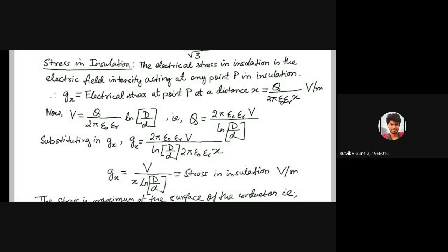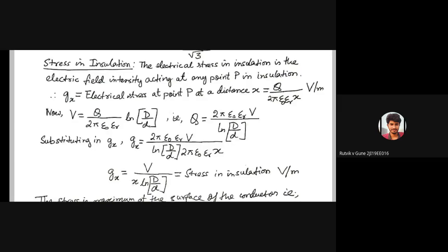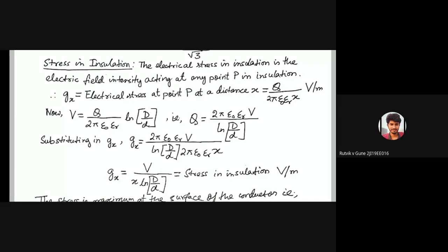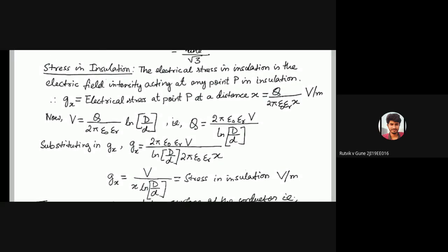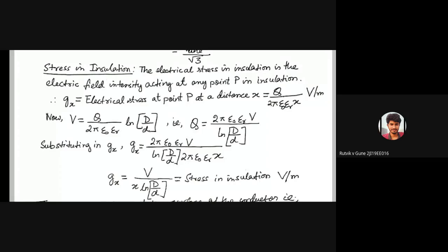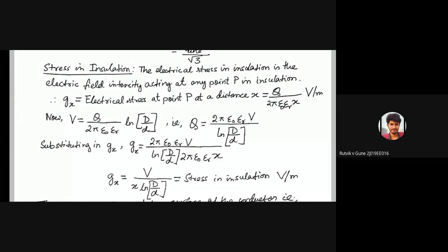As the core carries the current, there will be leakage current anyway. However strong insulation you make, there will be some amount of current flowing. So obviously, there is a very huge amount of stress within the insulation. It has to protect, and leakage current is happening anyway. So how will it protect? The insulation layer has this huge amount of stress.